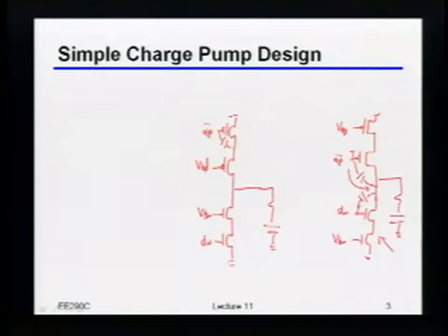I'll give you maybe a hint. Since you want this output to be referenced to ground, what would you like to show up right here? Ground? Yeah, what if you put ground there, right? Because remember, this switch is supposed to be off, right? It's supposed to be like a current source. So indeed, you could basically do something like that, right? Just shut the thing off, right?